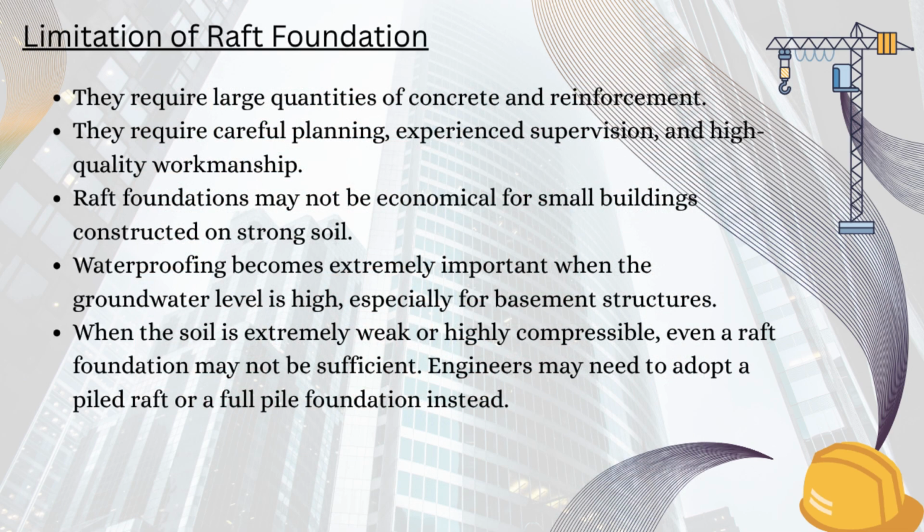Although raft foundations offer many advantages, they also have some limitations. They require large quantities of concrete and reinforcement, making the initial construction cost higher than pad or strip foundations. They require careful planning, experienced supervision, and high-quality workmanship, because construction errors are difficult and expensive to repair after concreting.